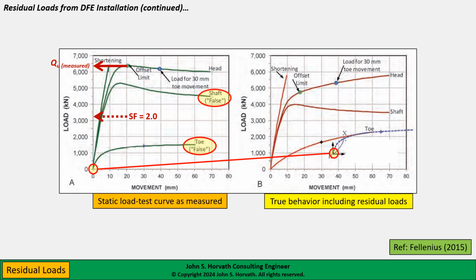Well, similarly, the shaft resistance shown here is false. It's too large, because to some extent we're double counting the shaft resistance. Right? Think back to what I showed you a few slides ago for the NGI test pile, where in the upper roughly 8 meters or so of the pile, when we went from end of driving to geotechnical failure, we had to move the shaft resistance from full negative, down drag, to neutral, to positive resistance, positive shaft friction or resistance.